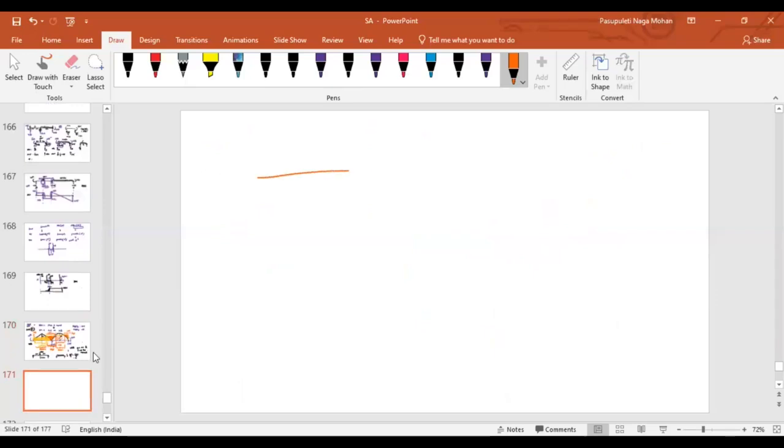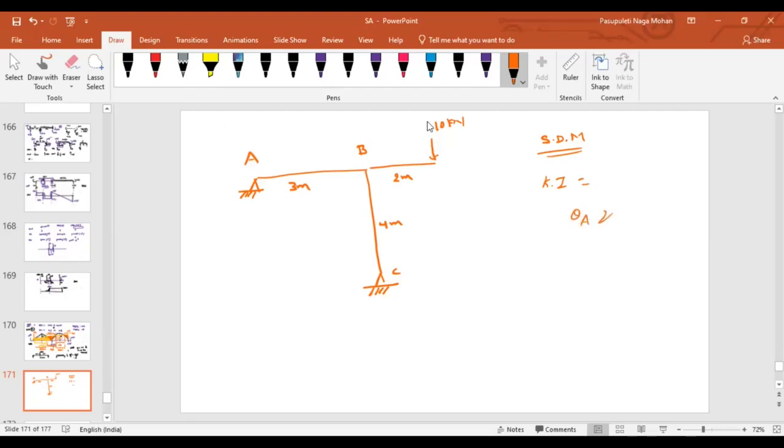Okay. So if you have any doubts, let me know, or else I'll ask you to solve one simple example. If you want to solve this using the slope deflection method, can you tell me how many unknowns you have to consider? Am I audible? Yes, sir. Unknowns, in the sense you are asking, are the kinematic indeterminacy. If I'm talking about static indeterminacy, that's different; the kinematic indeterminacy gives our unknowns. Okay, sir. So what are those unknowns? Can you quickly find it out? One thing I am sure of: rotation at A, rotation at B, and rotation at C. What about at point D?